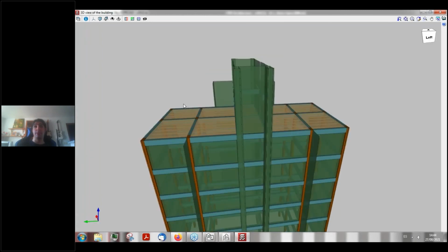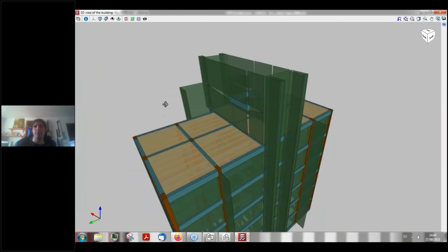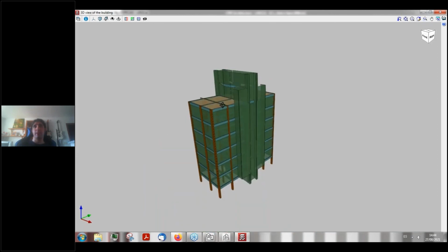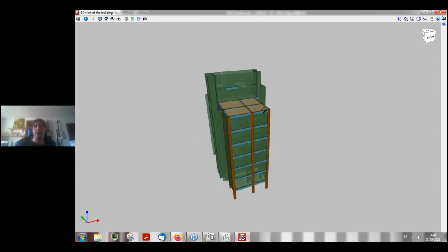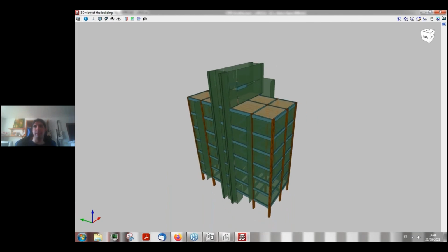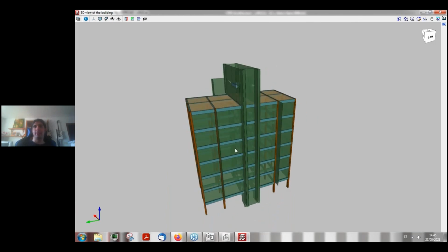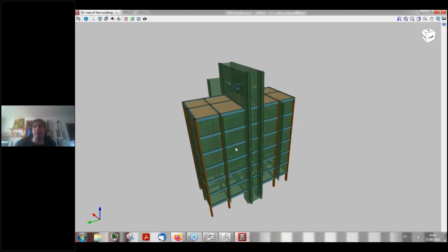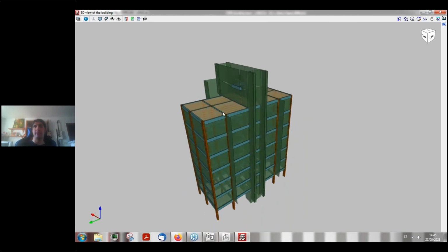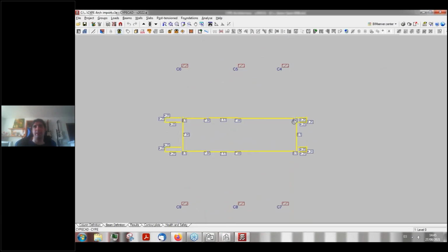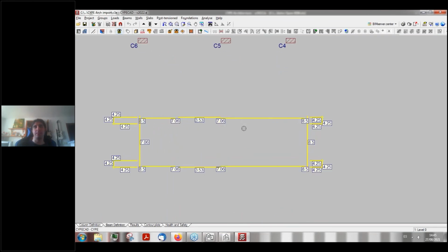We've turned this model, made in CYPE Architecture, into something understandable by CYPECAD. And from then on, if we were to tweak this model, we could create a final analysis for our structure. So with just one basic model of our building made in CYPE Architecture, we could use that very same IFC file to generate new IFC files, like the one that I could generate from right here. As you can see, all the elements have been imported correctly, and most of the data has been recycled from what I've inserted here in CYPE Architecture.